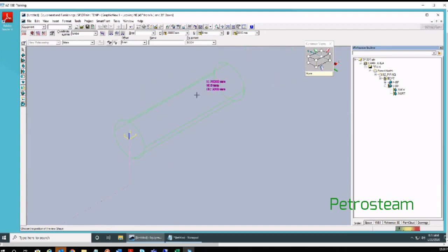It is showing you graphics for the cylinder, how it will look. The preview is available. Okay, you have not yet completed the command. You selected the command for placement, you selected the parent for that, and after that it gave you options to input the properties. Once you input the properties, you are here. It is showing the preview of how it will be placed if you place it as it is.